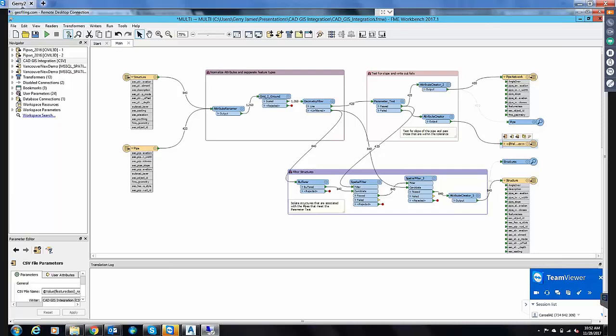One of the standard ways of doing this in the past has been to export data out to SDF. Then you have to create that FDO connection with SDF in the Civil 3D environment and do bulk copy into shapefiles. And then those shapefiles can be brought in. That's a lot of steps and really hard to automate in that Autodesk environment. So this will remove that requirement and allow people to automate this.